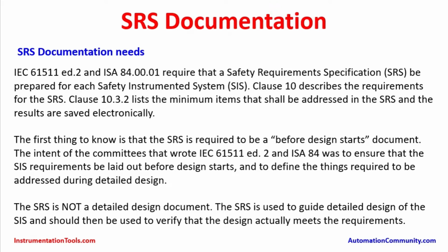Okay, the SRS is not a detailed design document. The SRS is used to guide the detailed design of the SIS, safety instrumented system, and then be used to verify that the design actually meets the requirements. It is a supporting document. It's not a basic design document for the safety system, protection system and all. It will have its own topology and design principles based on which the sensors, logic solver and final elements, configurations, the logic solvers, different types of logics or mathematical computations will be mentioned. And the SRS is a supporting document used for safety instrumented system testing, commissioning, etc.